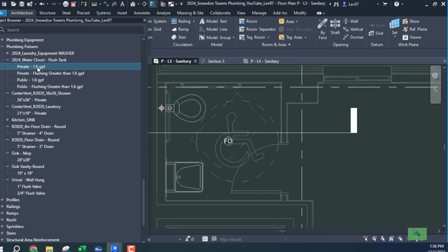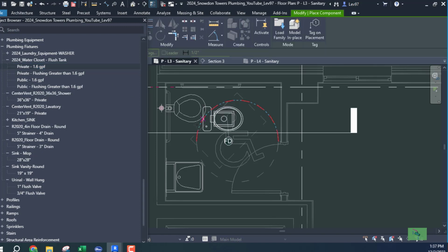The other thing I was thinking of was flush valve, and I couldn't for the life of me bring that into focus in my mind. But what I was thinking of was that I didn't need a flush tank. I needed that other one, which wasn't the case. I need the flush tank. The one that I wasn't thinking of, which I shouldn't have been thinking about, was the flush valve. And usually the wall-hung water closets are on the flush valve and not a flush tank. So I'm looking for this flush tank here, okay?